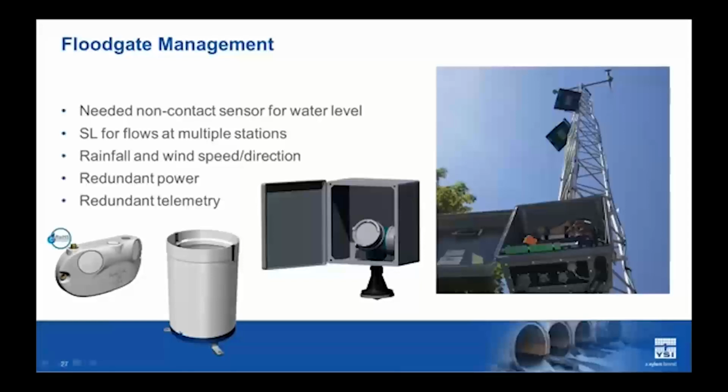So they put in a Sontek side looker, similar to the IQ, but with a different positioning, doing Doppler radar for looking at flow. And they had multiple stations that combined the side looker with the radar, as well as a tipping bucket rain gauge, so that they were always keeping an eye on the local rainfall.